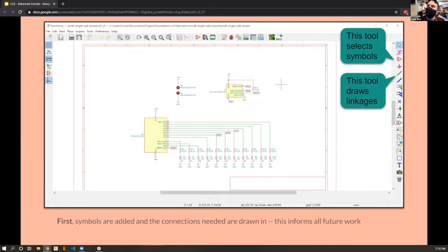And so in here, I've got just a few pieces, and drawing this has its own whole set of nuance. But it informs everything. So KiCad does a really nice job of putting the schematic up front, because when you draw your schematic, whether you're copying it from somewhere else or drawing it all your own, that's where you lay down all of the important information about what connects to what in the circuit.